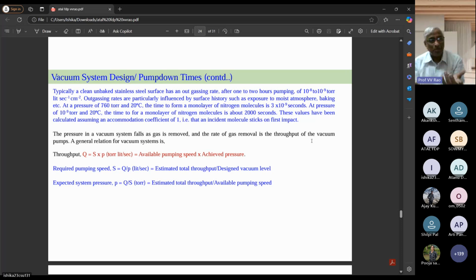If you are having only one pump, then the connecting pipes should have very good conductance. But at the same time, if the cost of the pipe goes up, then again it's not allowed. So you have to continuously use, in a reiterative manner, the design estimation of it. That is where the intelligence lies, and sometimes artificial intelligence. Okay. Next slide.